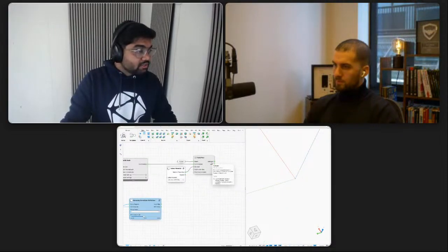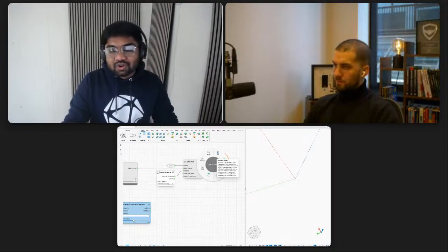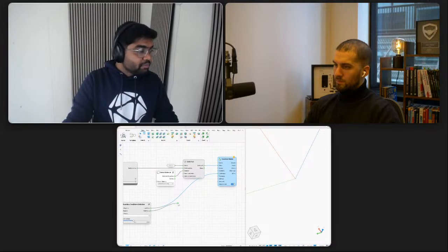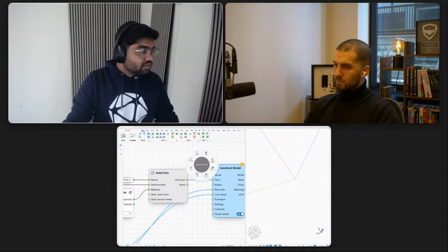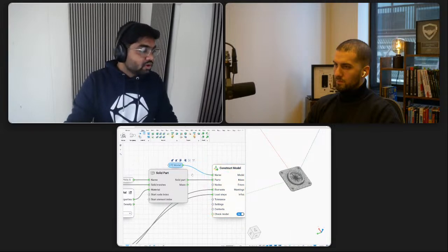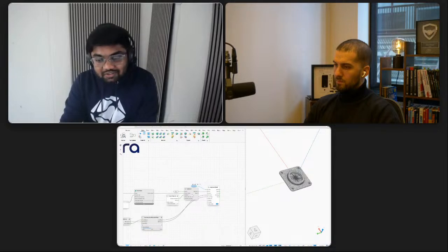Here we have the mesh. All we have to do next is just construct the model, assemble everything, give the mesh, assign the material, the load step. And then there's also a multi-point constraint, which is RBE here. Of course, one has to give a name here. So let's give it FE model. So that was quick to construct an FE model here.